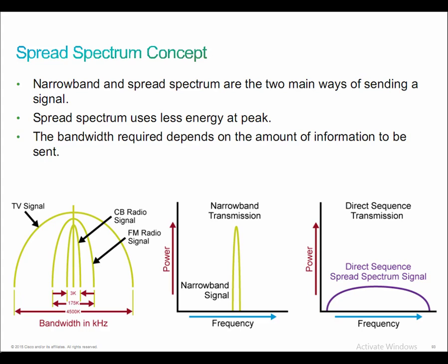But in that second technique that I mentioned, interference is overcome by sending a signal around the interference. So instead of sending one signal at a peak frequency like 2.412 gigahertz, like I mentioned before, the signal gets spread over a large frequency band. The same information gets sent, but on all frequencies that fall within a particular range.